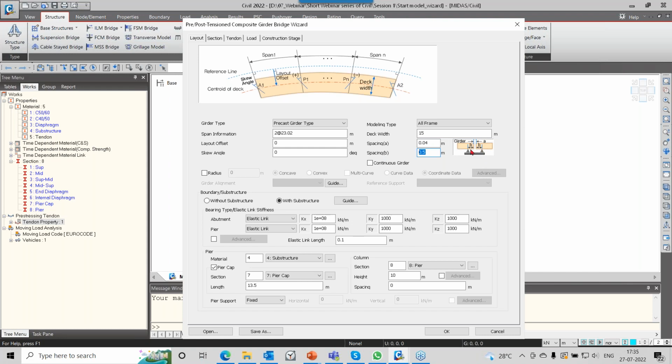500 mm, 0.5 meter between the edge of the span and the center of the support. So this one was not actually modeled in the manual, but you can definitely do that very easily in the manual modeling approach too. Okay, then further we have the option to make the girder continuous or not with just one checkbox. Curved or skewed types of bridges can be easily modeled.